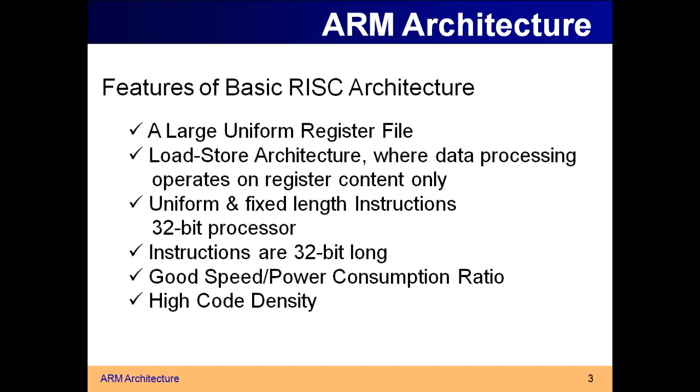So you are loading the data from the memory to a set of registers. From the registers the data will be going to the ALU, where the operation is done, and the result will be stored back to the memory, that is known as store operation. That is known as load store architecture.